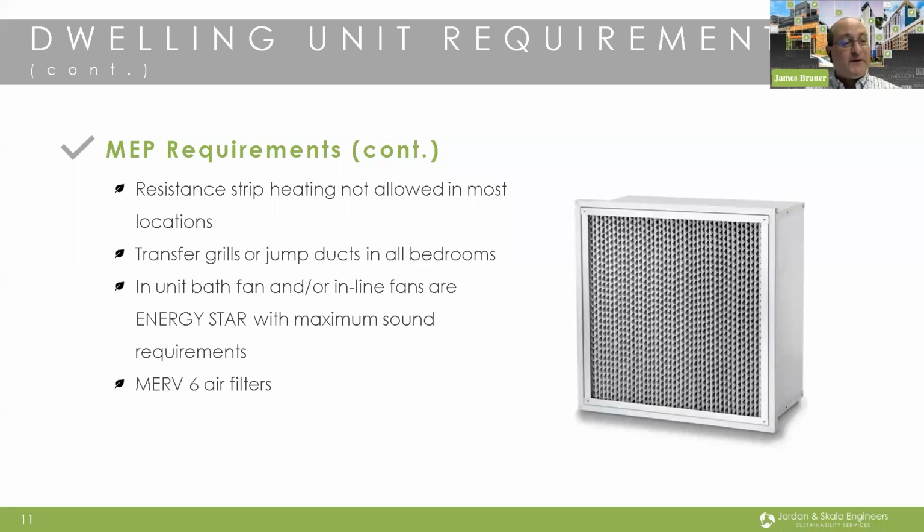So there's a requirement that there be transfer grills or jump ducts within all your bedrooms. Another performance item is that all in-unit bath fans or inline fans that are used need to be Energy Star rated, with a maximum sound requirement. Since we're focused on making sure that the right amount of air is being delivered, no one wants to hear a jet engine sound because of this. So the Energy Star maximum sound requirement will help abate any sound issues. Another indoor air quality measure that Energy Star asks for is a minimum of MERV 6 air filtration, so that we can certainly pick up and clean some of the air as it's being cycled through.